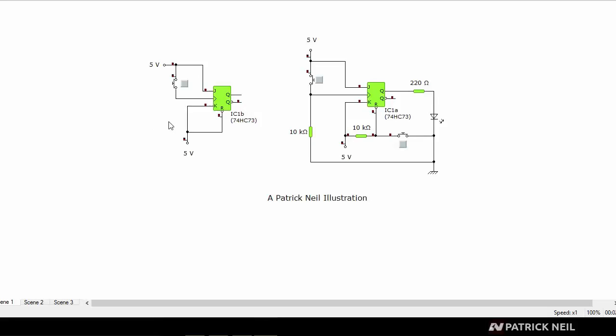Now in the real world, when you're designing your circuits, you must connect the pin to negative or ground for you to see low. You will not see low and your circuit will not work. You cannot leave the pin floating and have it considered low. It doesn't work like that. So for the sake of simplicity here, I'm not cluttering up my circuit, so I can explain flip-flops.